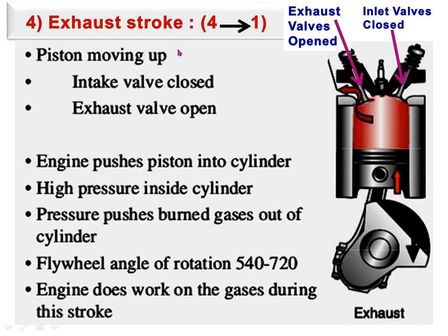See the phenomena of the exhaust stroke, from 4 to 1. The piston moves up, from bottom dead center to top dead center. Intake valve closed, exhaust valve open. The engine pushes the piston into the cylinder. The piston is pushed upward inside the cylinder.